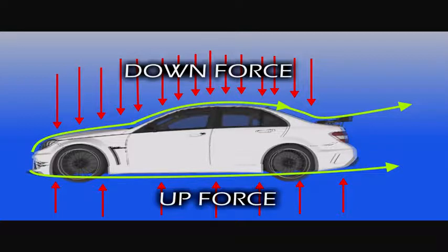The smaller volume of air that's available underneath the car allows for a greater downforce created by the air as compared to an upforce. So the greater downforce allows your car to stick to the road. It allows a good amount of traction in your tires due to the force pushing down on your car. It's what keeps you on the road at pretty high speeds.